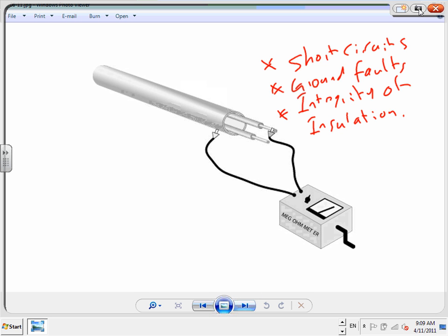The Megger is one machine. They have current generators. They call them current generators. Load banks. They have tons of other machines. A current generator pumps 50,000 amps of short circuit into the panel, and it makes sure the mains are going to trip. Okay, you said you are an engineer. You said this is going to trip at 50,000. Let's generate 50,000 amps of current, and they pump it into this panel and watch the circuit breaker, bam, tripping.